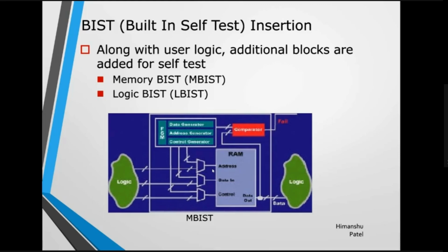What you try to add is additional connectivity to have a bypass. Bypass means this is a functional path and this is your testing path. You just add a mux to gain access to the same pin without disturbing the functional path. The select line of this mux is connected to a test mode signal, where you say mbist enable or mbist disable.